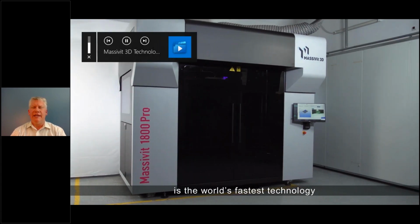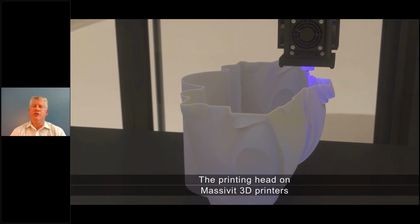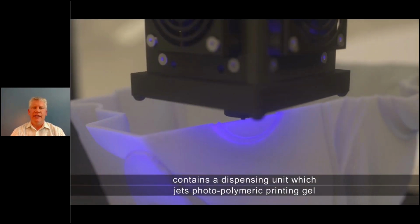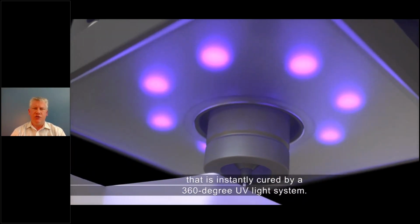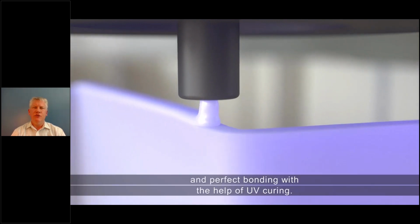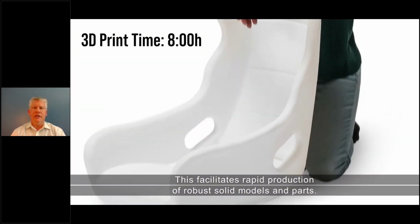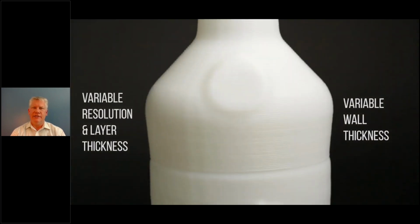What you see here is the Massivit 1800 Pro printer. It's the same printer style that you're going to see in a live demo in a minute. You can see that the gel is being extruded through a dispensing head. That dispensing head can control the position and location of that gel being applied. And then the UV light surrounds that gel so it can be cured instantly. That allows us to build very quickly, as you've seen, tall parts in hours, not days.